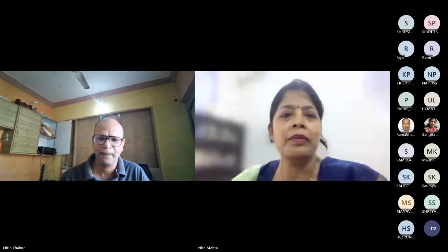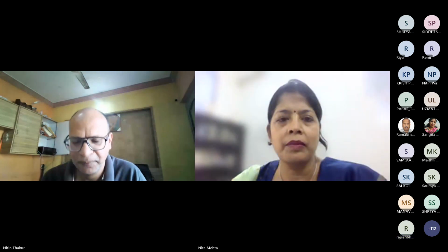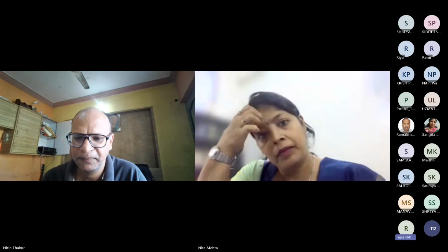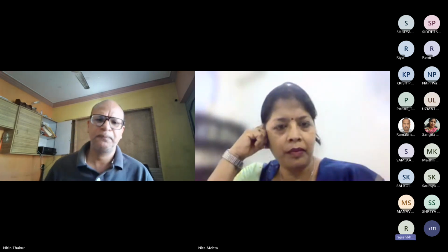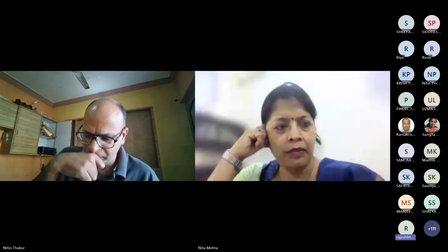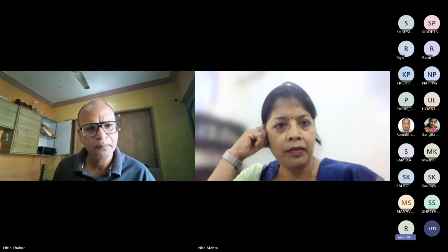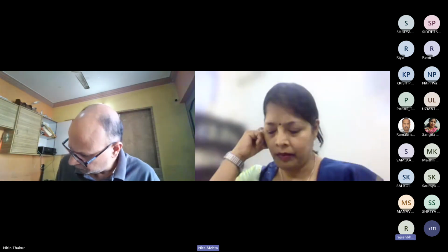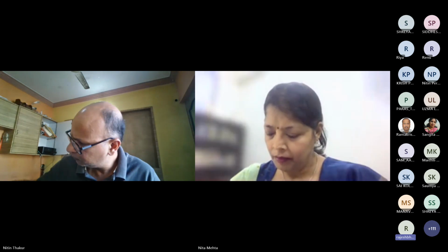Thakur Sahab, Rajesh here. I'm from an oil and gas EPC background. This problem is related to human lives in Delhi. One point, based on my experience: there is scaling, and the scale is coming out of the steam. Generally it will be calcium and magnesium sulfates and chlorides. These scales we generally find in boilers.